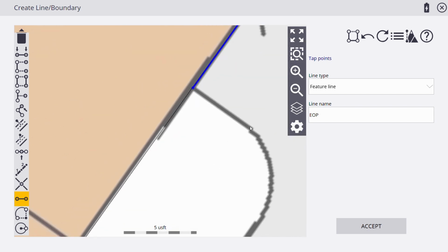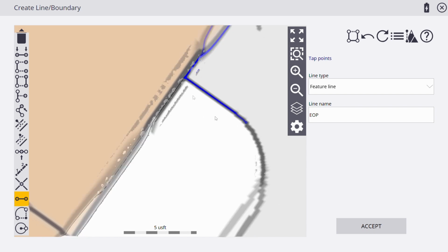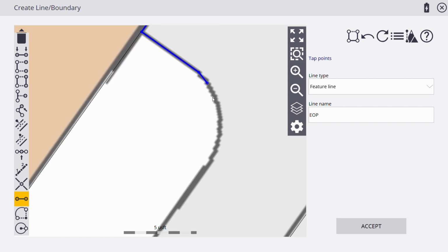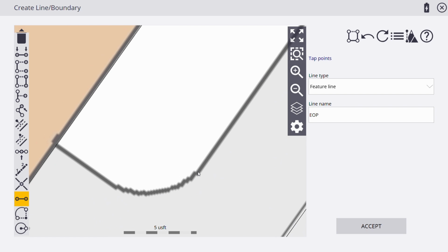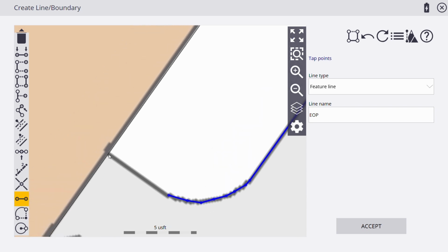And now most of the time you'll see that the building line is off the PDF a little bit. Most of the time you're over digging anyways, and the contractor's not responsible for pinning this foundation or concrete. If you're lucky beforehand, someone will have come and staked where the building was. It'll give you a little bit firmer reference point, but dimensionally is exactly where it needs to be.